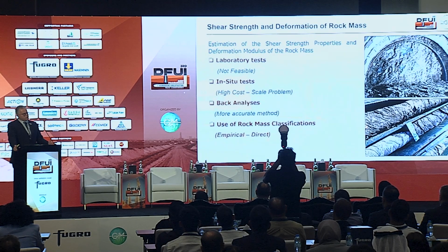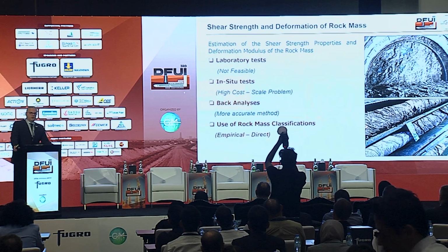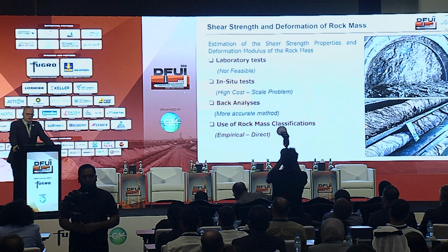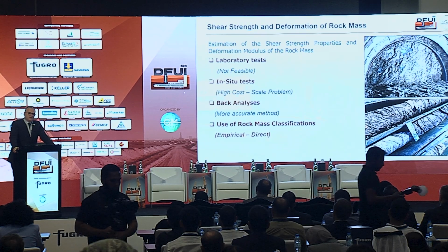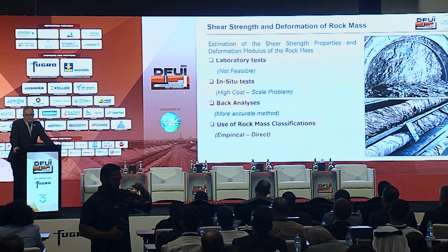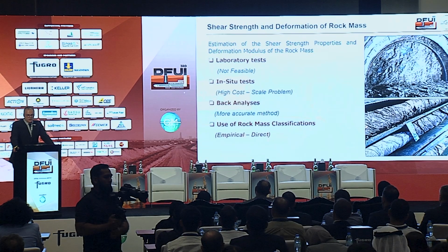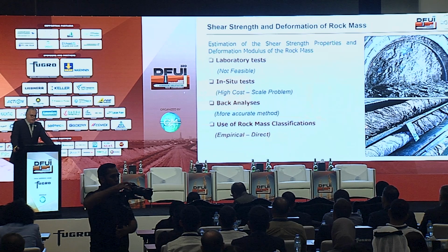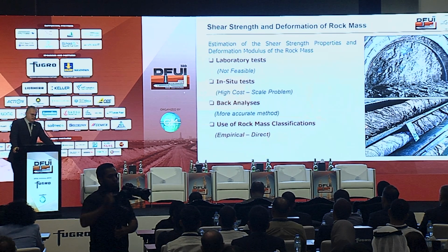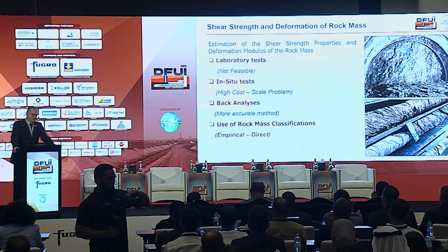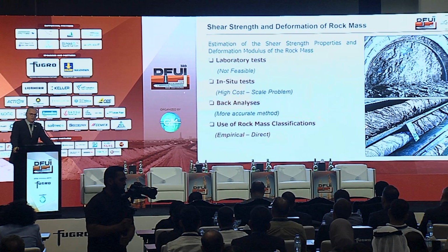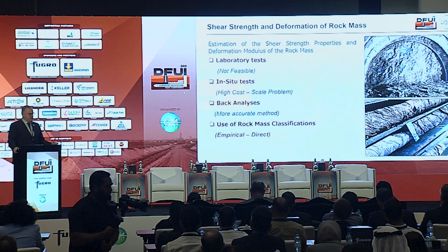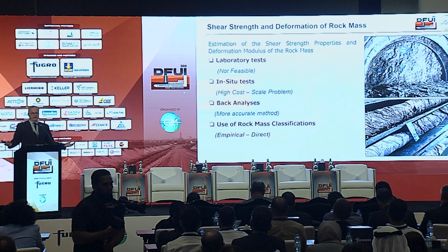In rock mass characterization, we have a problem with laboratory tests: we can only measure the intact rock, so this is often not feasible. In situ tests are very expensive, or we have a scale effect. Back analysis is of course the best way to characterize a material, but you need a failure or some deformation to back analyze, and your project is already running.